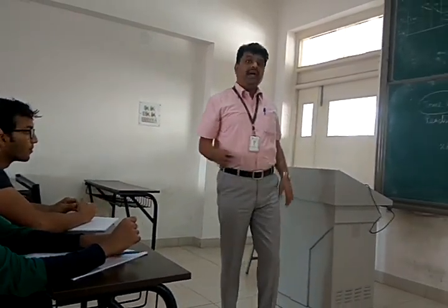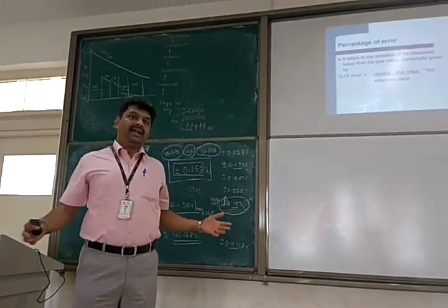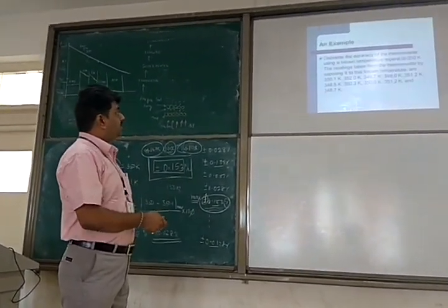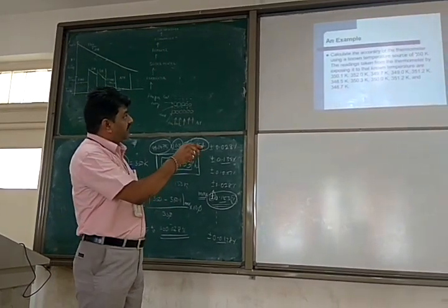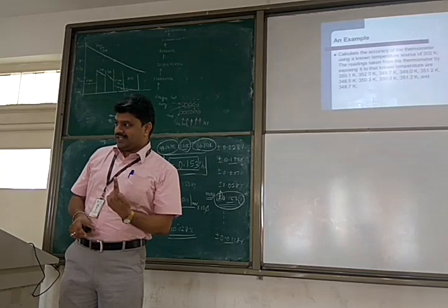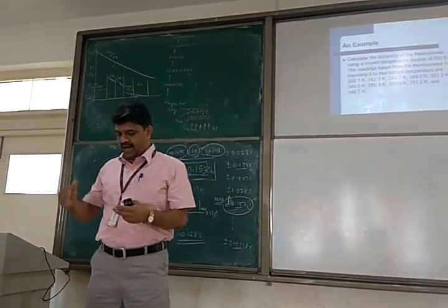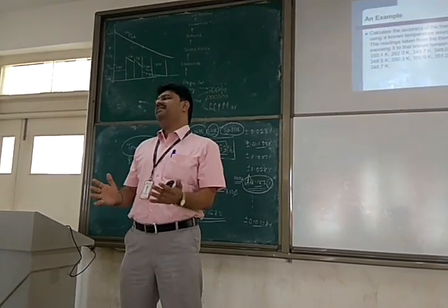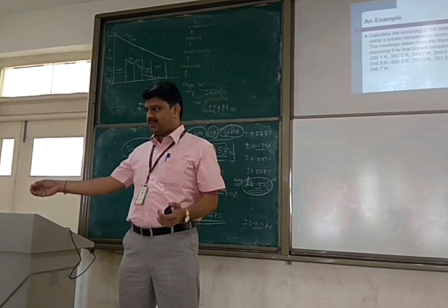See this, he is telling, sir, when we measure a smaller value and a bigger value, here the inaccuracy is more. See, I have taken a reference value of 350, one reference value. With respect to that, I have a medium, exactly made to 350 Kelvin. And I am using my instrument to be calibrated.